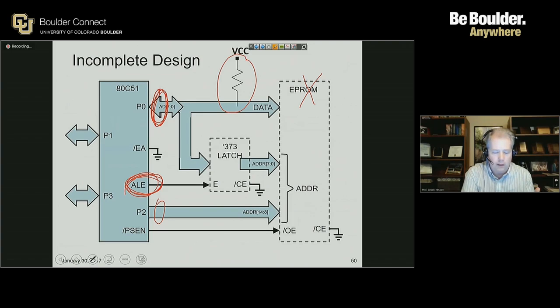So instead of 1.8 megahertz, it may be oscillating at 3.6 megahertz. If it's oscillating at something other than 1/6 of the crystal frequency, then you need to fix it. You need to tune it. You need to adjust the load capacitance, get it to a point where every single time you turn on power to your system, it always comes up at the right frequency. That is something you have to do.